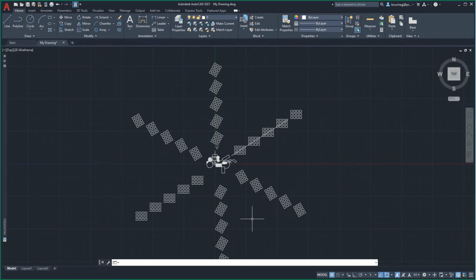Below the fillet chamfer icons in the Modify panel is the Array command. The Array command provides the ability to make copies of objects and arrange them in a controlled and defined pattern. A rectangular array distributes the copies of a base object in a series of columns or rows. The polar array evenly distributes the copies of a selected object about a circular path from a selected center point. The path array distributes the copies of a selected object along a predefined path.